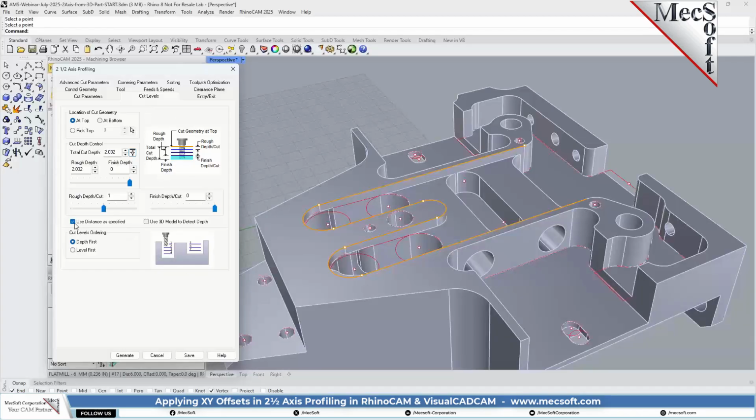The reason that we added this recently, I'm not sure if that was recent or not, Joe, but you really at times want to control how deep you're cutting, depending on the geometry and depending on the operation that you're using. The actual depth may not come out to the actual depth that you're wanting it to, just based on how it calculates the overall depth, and how much material is to remove and stuff.